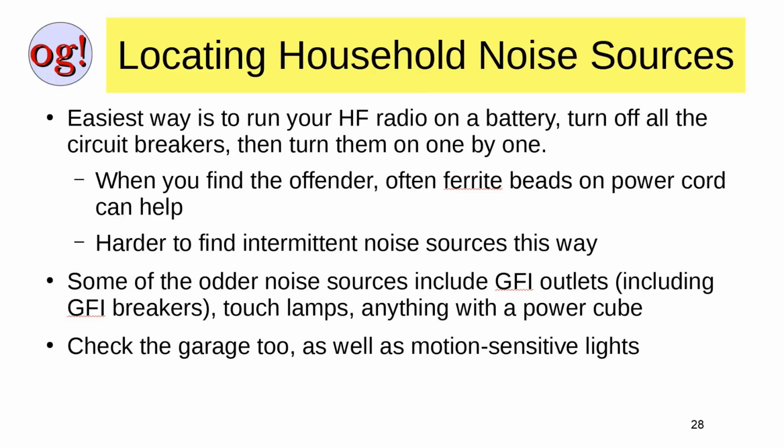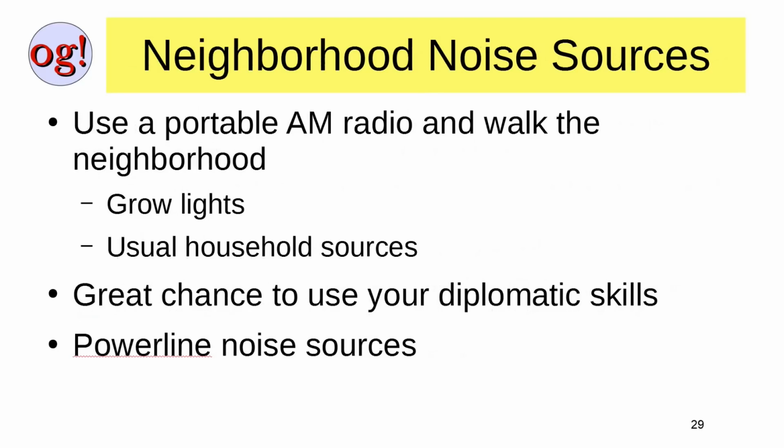Some of the odder noise sources to look for include GFI outlets, including GFI breakers. They'll sometimes have, oddly enough, some electronics in them. Touch lamps, of course, and anything with a power cube. Check the garage too, as well as motion-sensitive lights.